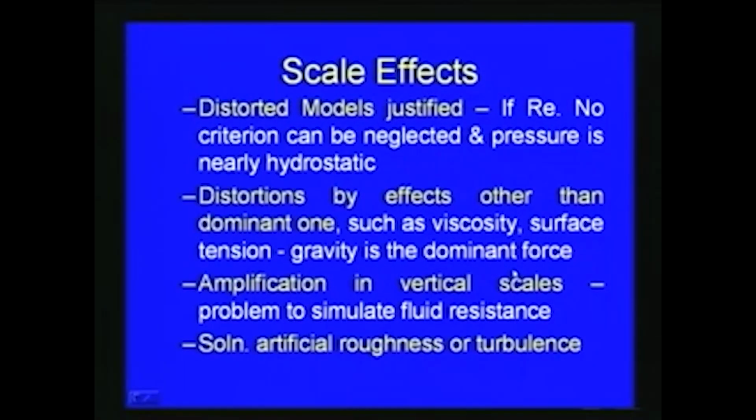While doing these kinds of models, we should be very careful that scale effects are considered, and the corresponding rectification is done before the model results are transferred to the prototype, either for design or for construction purposes.